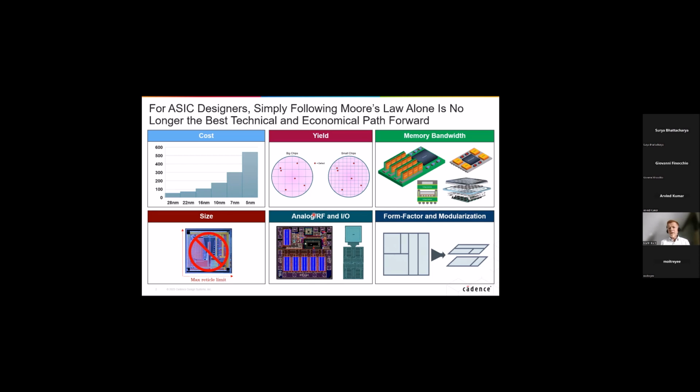So even in 2011, NVIDIA disaggregated a larger FPGA into 4 smaller chips to get a better yield and performance. Another motivation to go to heterogeneous integration is the memory bandwidth. We also heard the closer the memory is to the processor, the better. So if you need more memory, putting it on a PCB may not be the best option. You need to be closer, either HBM memories on a silicon interposer or even in a stack configuration.